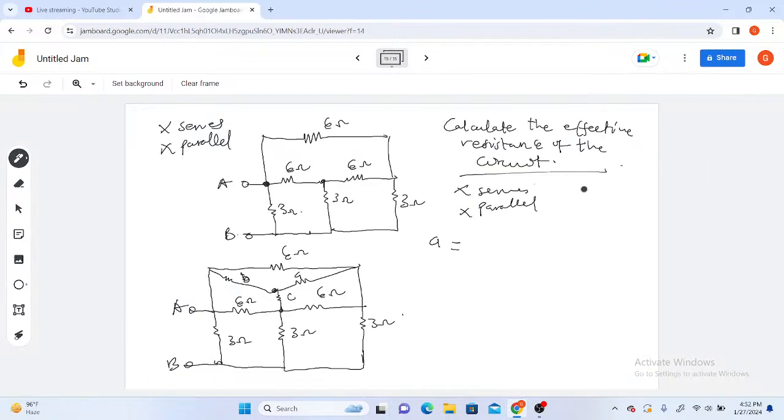So please see, A is between 6 ohm and 6 ohm. So to find the value, you get 6 by 6 over 6 plus 6 plus 6, where this is the sum of all the three resistors, and this is the product of the two resistors which A finds itself between. This gives 36 over 18 and giving me 2 ohms, right?